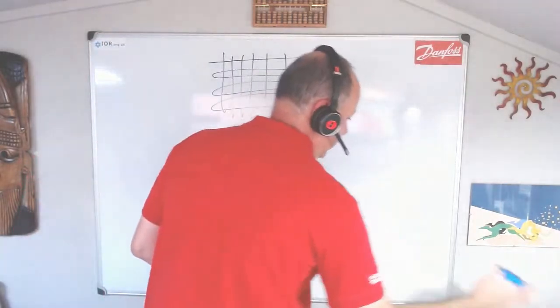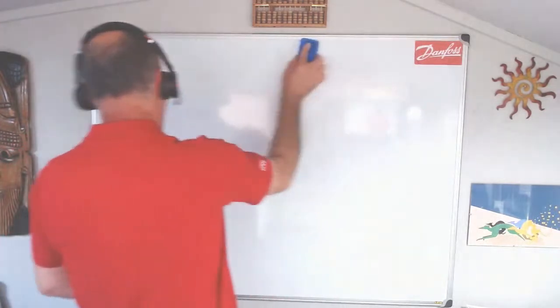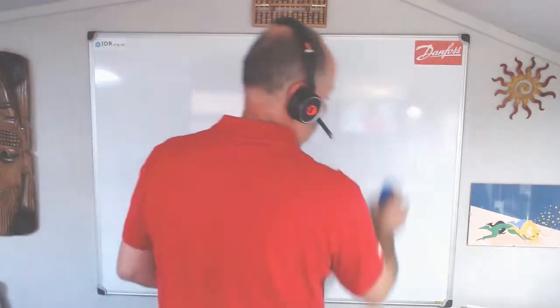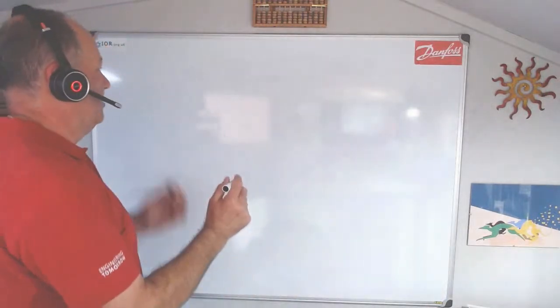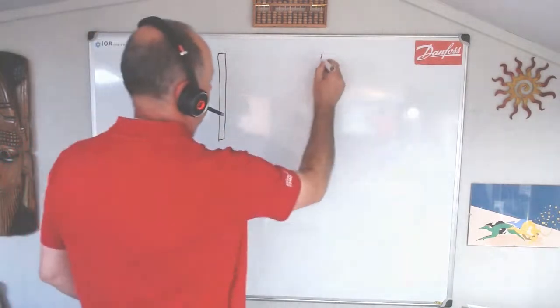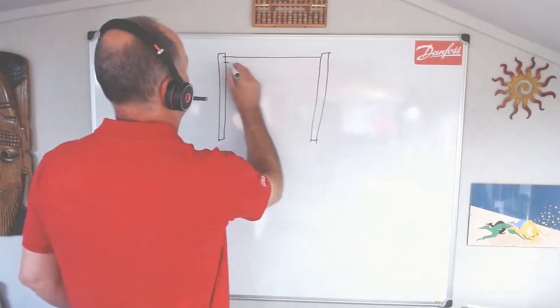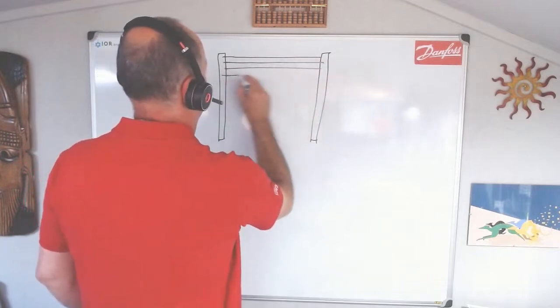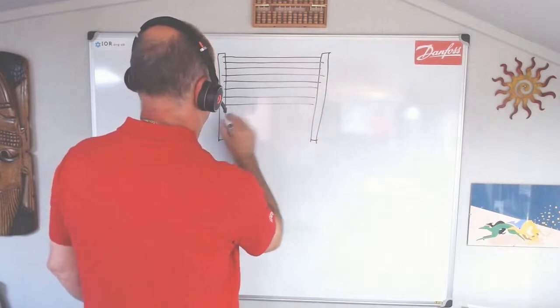Microchannel is a little bit different, and I've actually got one in here somewhere that I could dig out and show you on the webcam. But basically, with a microchannel, you have a header and another header, and you have a series of tubes, like so. I won't draw all of them. I know, I will. Tell a lie.